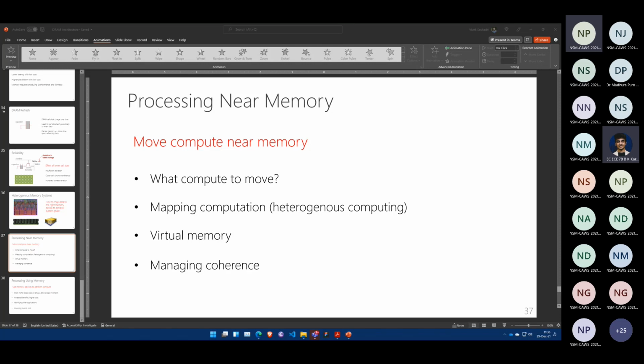Okay, so the memory controller will take care of which chip to locate. Yes. Which physical address should map to which bank, which row and which column. All those things are taken care of by the memory controller. So the memory controller is not just a decoder; it is much more than a decoder. It will have some kind of acknowledging unit also. Not only a decoder, but there will be some kind of.